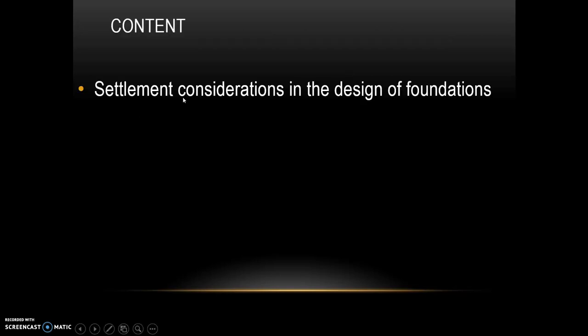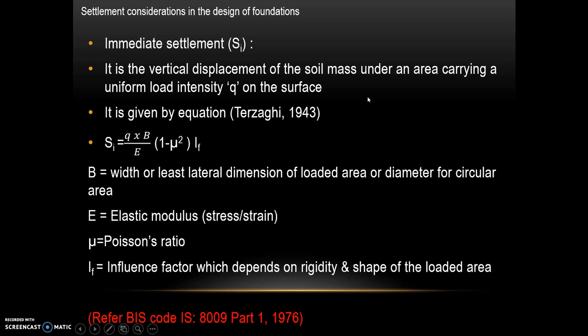In this presentation, we will go through settlement considerations in the design of foundations. We know that the total settlement of soil under any loading is the sum of immediate settlement and consolidation settlement. Now we will find out how to get the value of immediate settlement, which is represented by SI.